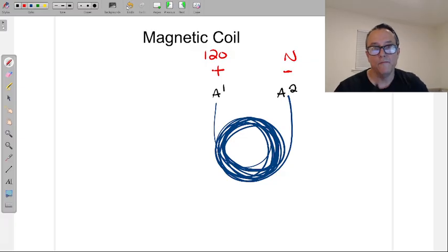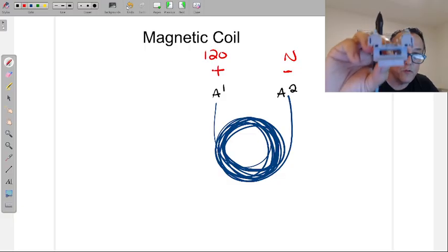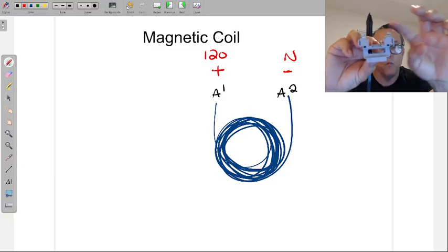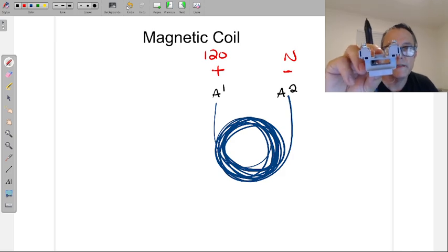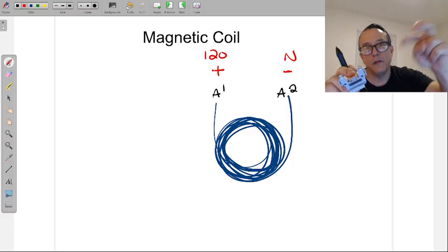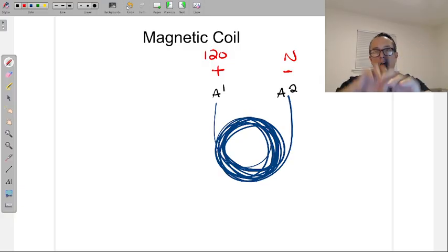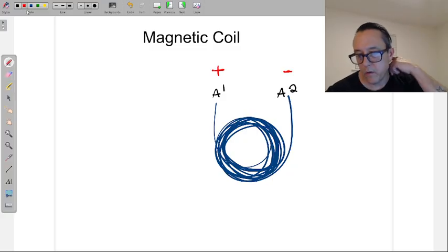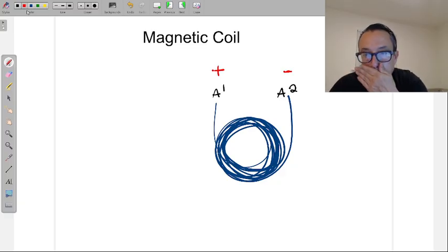So, for example, if you put 120 volts on this 24 volt DC rated coil, mistakenly, then I burn this coil out because the coiled wire is too short. It was designed for 24 volts DC. And vice versa. If I put 24 volts DC on the 120 volt coil, there's just too much coil now to get the effect that we're looking for. So I'm just going to leave positive and negative here, because it's easier than continuing to say 120 neutral or hot neutral. Just put positive, negative, and everybody should hopefully understand that.